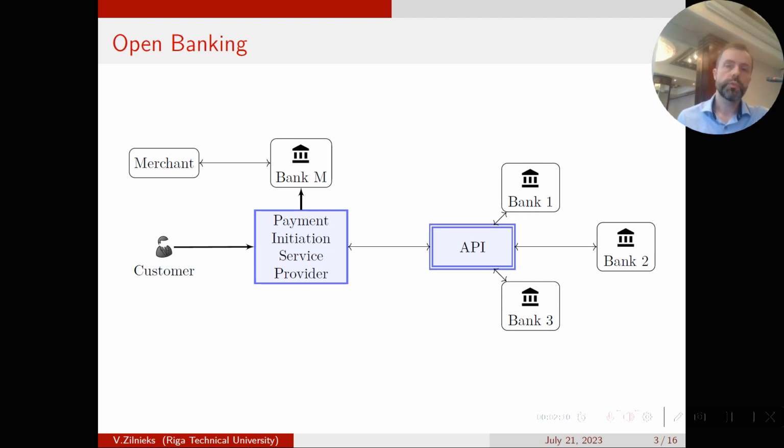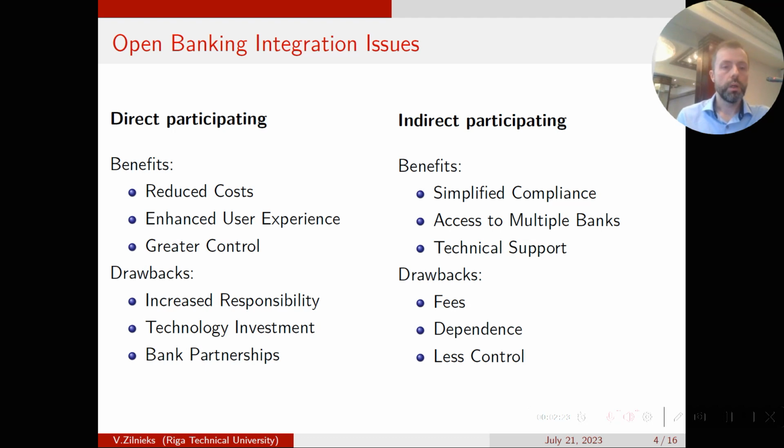The indoor ambient is defined using a lumped thermal system, and the indoor air is subject to three loads: ventilation load, heating load by fan coils, and also the diffusive heat due to transmission across the wall.